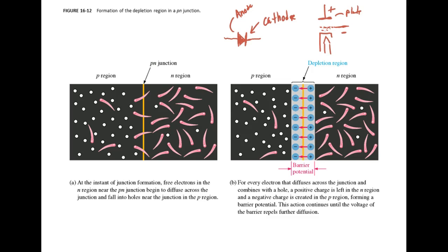And so we can make it amplify signals, right? I take a tiny signal and put it right here, because the grid was right on top of the cathode, and the anode was way up here. With a very small grid voltage, not a current, a voltage, we can control a lot of current between the cathode and the anode, which means I could take a real small current and get a large current out.